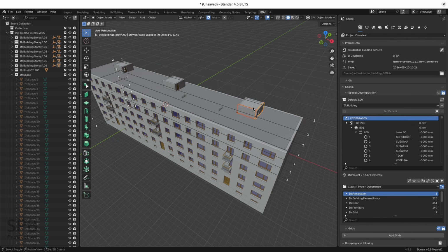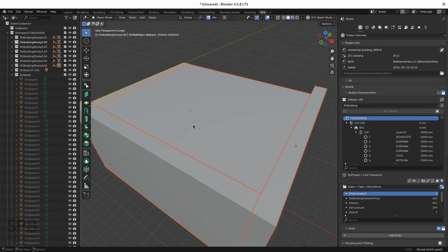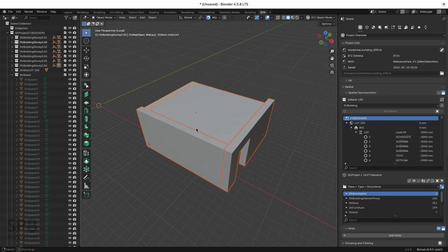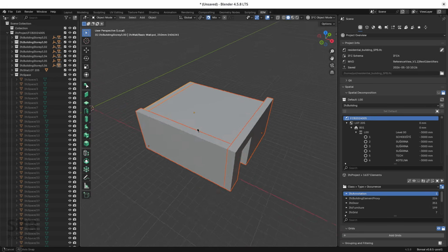So let's say I will select these 4 objects again and I want to explore them, and to isolate just these objects I will press the slash button on my numpad, and if I press it I'm zoomed in on the selected objects, and those other objects are not visible, they are hidden.